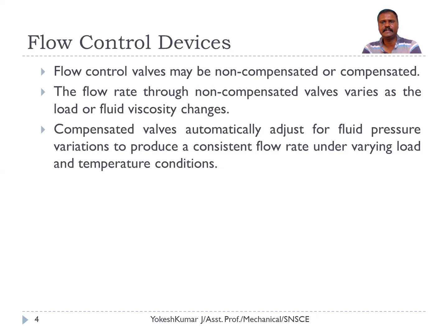If the bin is empty, then the back pressure created by the system is very less. Therefore, the pressure difference will be more because the pump is pumping the fluid at very high pressure. So, since there is a very high pressure difference, the flow rate will be very high. So, therefore, we cannot ensure that the flow rate is constant for all the times since the load is constantly changing. On the other hand, viscosity also plays a vital role